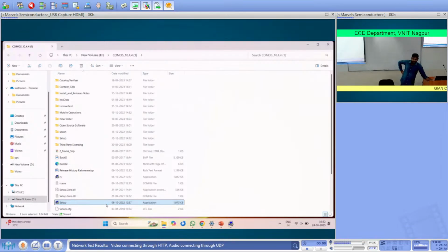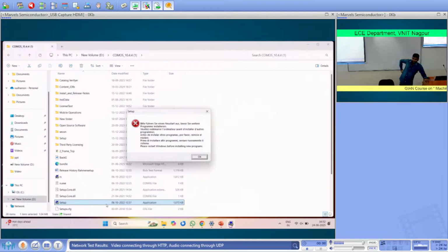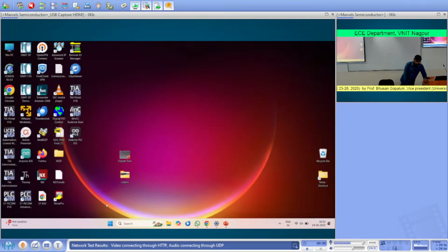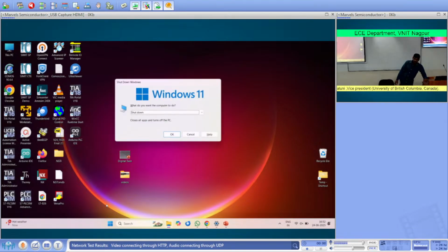Hello, sir, just one question. I understand the mechanism, how digital twins work. So the question is, will this software be installed in the DCS itself, or will it have altogether a different server, and to that server all the sensors in the plant will be interacting? For instance, if I have removed the pump from some pipeline, how does my digital twin come to know that a pump has been removed from the pipeline?